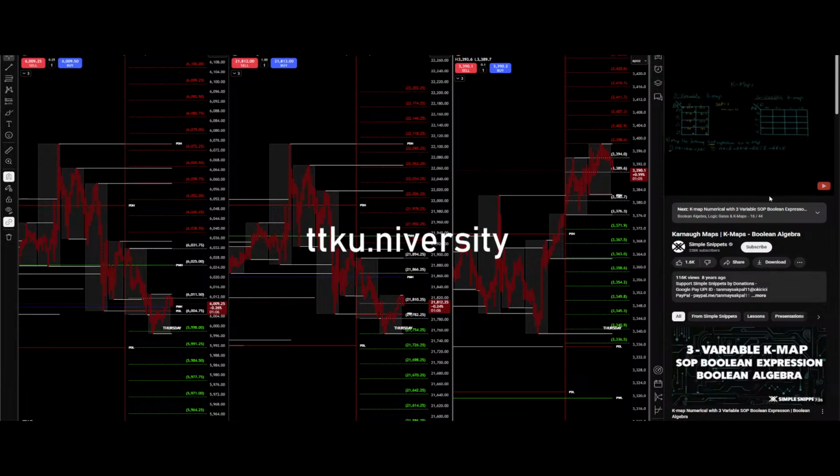Now if you have missed the part where we discussed SOP and POS, we have a separate video wherein we understand its concept and we convert different Boolean algebraic expressions into SOP and POS forms in the previous video tutorials from this playlist. So you can check it out as well. So now with that concept, we need to map each of these terms into the K-map and represent it by number 1, since it is SOP and it is associated with the number 1. So the first term ABC means that all values are 1.